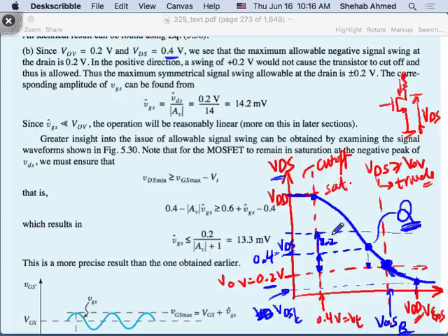Yes, ma'am. Are we always allowed the overdrive voltage swing? Because this is the value. No, no. This is minimum. Yeah, you're allowed to go all the way. If your operating point was here, Q, you're allowed all of this on the negative side, but you're only allowed this on the positive side, right? So for it to be symmetric, then it has to be less. For it to be symmetric, it's good to be located between your overdrive voltage and VDD, halfway between overdrive voltage and VDD, for you to get your maximum swing, if you want to call it.